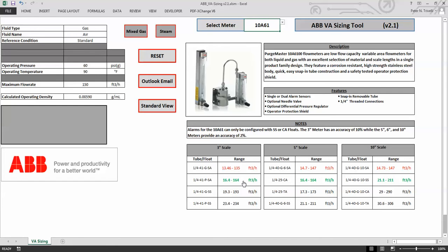The numbers in green are the result of a tube and flow combination that contains the full scale of the required maximum flow rate. These combinations are the best selections for 90% of your sizings. The red selections are also possible sizings, but do not include the full range requested. To see a detailed description of your sizing, click the sizing that you are interested in.